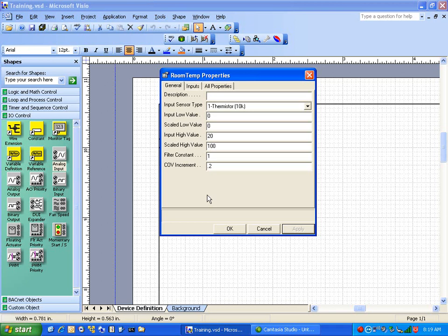In engineering practice, we double it. We go to 500, and we even go beyond that. We'll see some 700, 800, 900. And so what happens if COV is not being used, you can have a pretty bogged down BACnet network. So that's why it's very important.